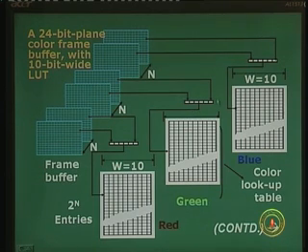What it basically means is we are talking of an n bit wide register, n in this case being 8, let us say. And so we have 2 to the power n entries for each color set of the frame buffer. Consider only red, only green, or only blue, any one of the 3 colors. We have n bit planes for red, let us say. We have an n bit register for the red, and the contents of the n bit register are fed as an entry to the lookup table. So you are looking at any one out of the 256 possible entries in the lookup table, because 2 to the power n, we have taken n to be 8. So 2 to the power 8, 256 entries are there in the lookup table for each channel, similarly for red, similarly for green, similarly for blue.